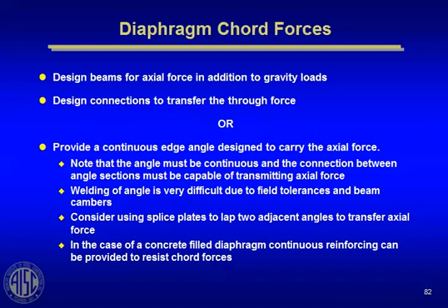or you can fasten the deck to the spandrel beam and have the spandrel beam serve as the chord element. If you go that direction, remember that when the spandrel beam ends at the column, you've got to carry that additional force through the connection, through the column, into the other side. You've got to be mindful of the spandrel beam connections if you go that route.